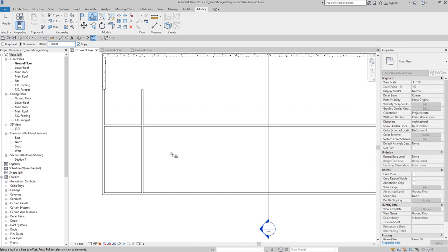Then I'm going to place the cursor over the horizontal internal wall so that the preview line appears below it, just like what I have right now. You see the preview is below, because if you move your pointer up, the preview will show that it's above, so make sure it's below. I'm going to click here to place the new wall. That's it.